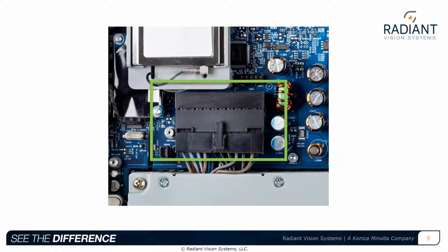Sometimes a defect doesn't cause an immediate part failure. Even if the device passes a functional test, a defect such as a loose connector may result in a latent failure after the device has been shipped. These types of defects may only be prevented by detecting very subtle deviations in the component's position, like a slightly angled connector that may not be fully attached.